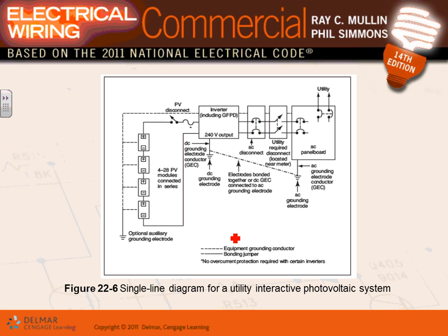Okay, here's how the system is wired, guys. Here are your solar panels, 28 volts each. They bring the positive and the negative. Can you see the positive and the negative? They have a disconnect here for safety, and an overcurrent protection device typically on the positive side. You bring it to the inverter and invert it to 240 volts. You have an AC disconnect here, and then you bring it into the utility with another AC disconnect for the utility. That's how you feed your power into the utility. Any comments, guys? Any questions?